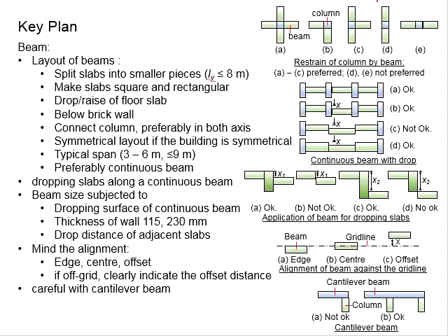However, sometimes this kind of arrangement may not be fully avoided, which normally we see in this kind of design. It is when the upper story does not have any significant load. For example, the beams for the roof at the car porch, only one story. There won't be a column extended above the car porch, and the loads onto the roof of the carport are relatively small, then you might not have a problem with the slenderness of the columns.